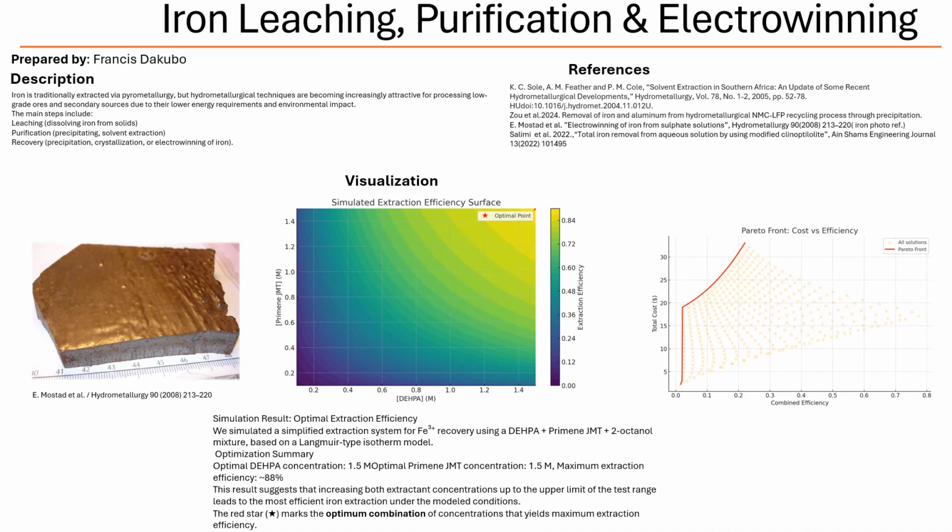So electrowinning, basically, you're running a current through a solution to deposit iron onto a cathode. Precisely. The pilot plant used iron starting sheets for the cathodes and lead anodes, separated by a diaphragm. Why the diaphragm? It's all about keeping things separate. At the cathode, you want ferrous iron, Fe2+, to be reduced to metallic iron and deposited. But you also have side reactions, like hydrogen ions turning into hydrogen gas, or ferric iron, Fe3+, being reduced back to ferrous. Okay, multiple reactions happening at the same time.